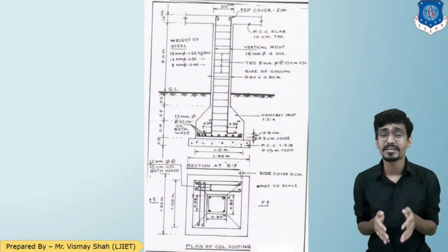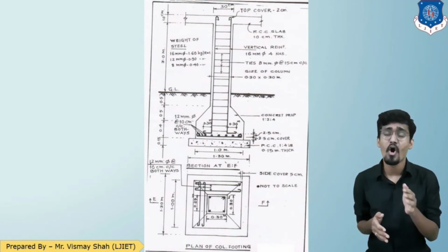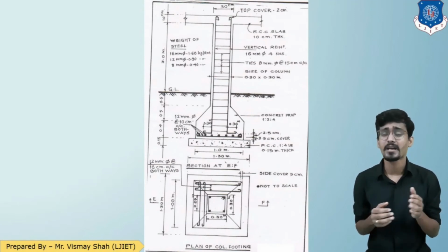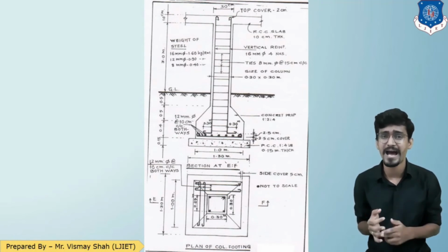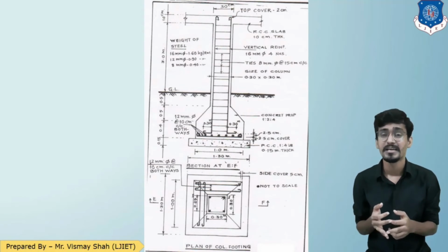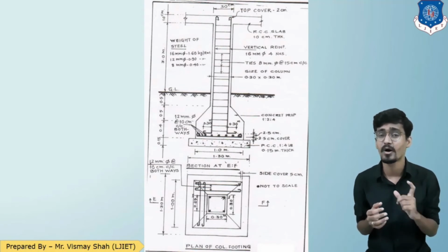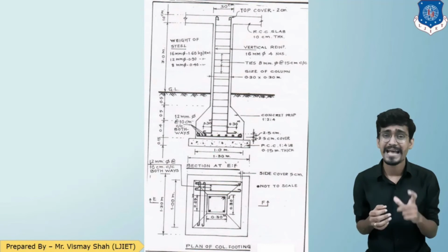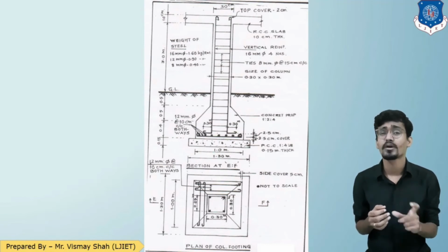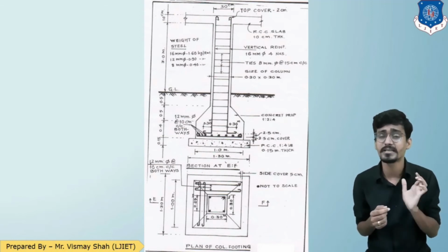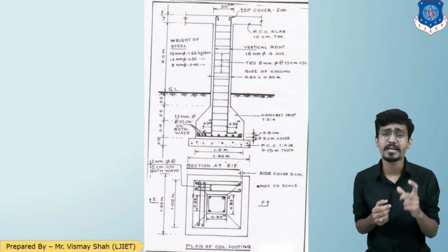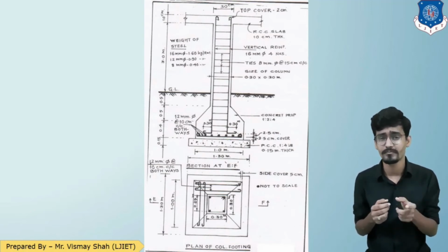As you can see in the section, let us consider all the vertical heights. So adding up all the vertical heights, 0.4 plus 0.5 plus 0.5 plus 3 meter. That is the entire vertical height of the column. But as we already know, the reinforcement of the column is placed after the deduction of the cover distance. So deducting the cover distance, 2.5 centimeter from the bottom.